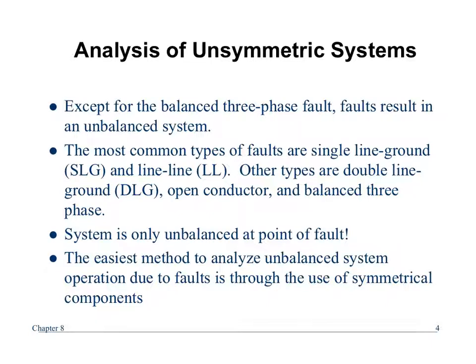I want to be able to detect those faults and take them out of service or take them offline. So there are some instances when you actually set some of your protection elements based on minimum fault current levels because you want to make sure you have the ability for your protection to actually see the fault, okay? So you actually have to do these other cases so that you can see minimum fault currents and then still be able to respond and trip those, okay? Not super common, but common enough that I've actually had to do that, all right? So something to think about when you do that. And then plus the other thing is it's not that much more effort to look at the other two faults, so we'll include them anyway.